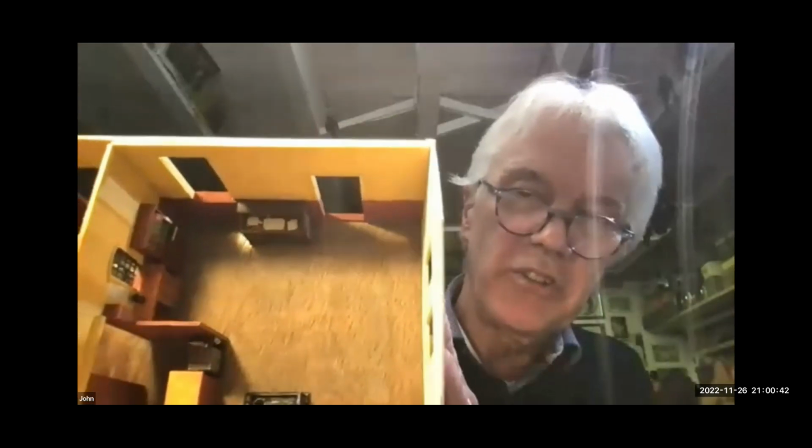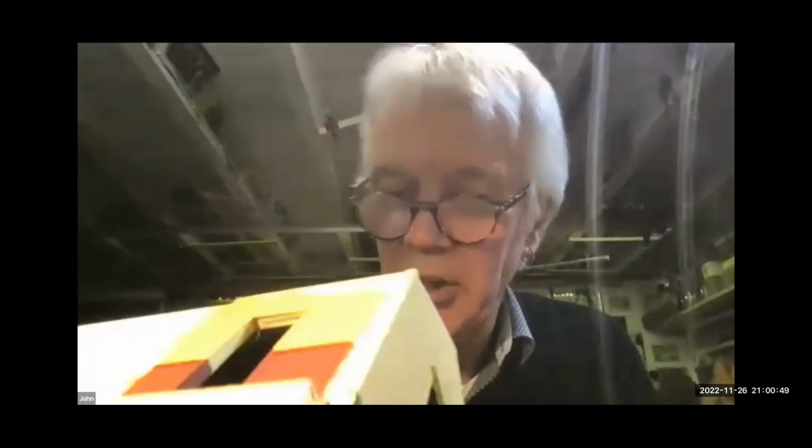You can paint it if you spray it with a primer. You can buy a can of plastic primer for use on cars, which is fine, or even an ordinary grey primer will do. It's more stable than ordinary card. It's waterproof. As you can see, it stands up very square, whereas a piece of card on the same thing would have bent over. It's as easy to cut as card, although it does seem to blunt blades quite quickly. It's stronger than card, but not as hard as plasticard, but I think it's more stable than plasticard.